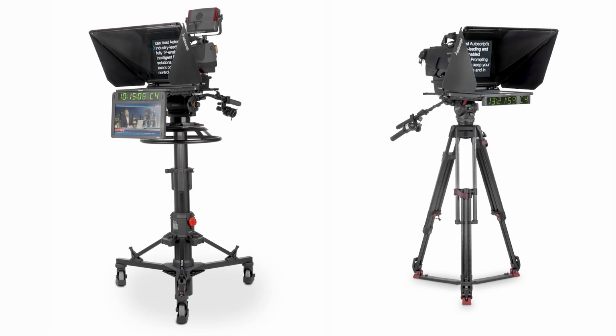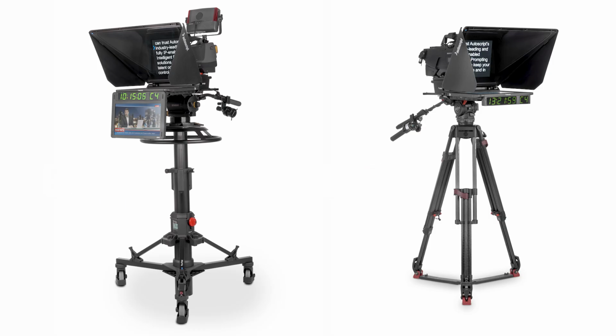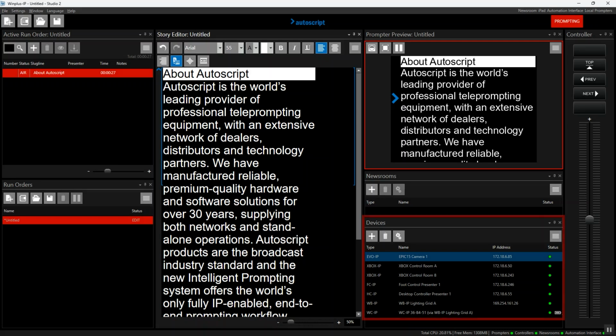When you have a CLOCKPLUS-IP connected as part of an EPIC or an ELO system, the clock configuration is done via the WinPlus-IP Devices pane. To do this, the prompter monitor must be connected to WinPlus via Ethernet. In the Devices window, select the monitor which the CLOCKPLUS is integrated to. In this example, we select a 15-inch EPIC monitor. Then click the Config button.